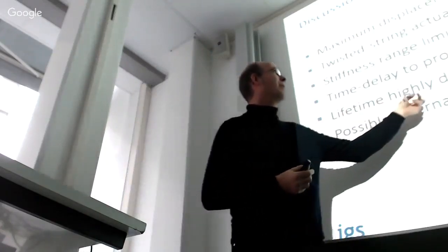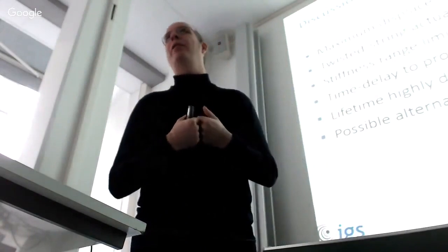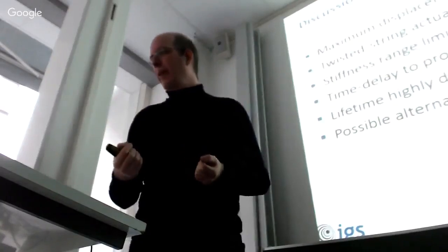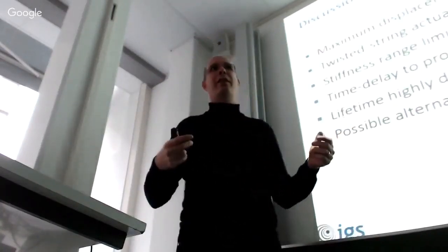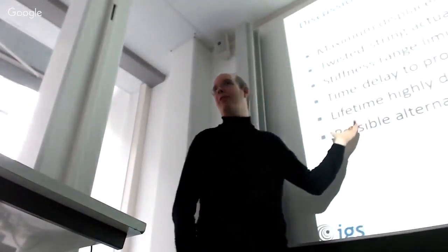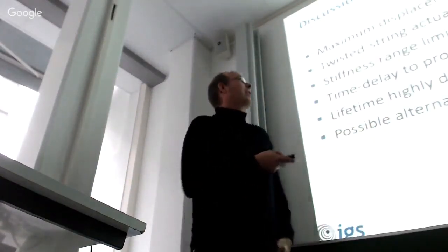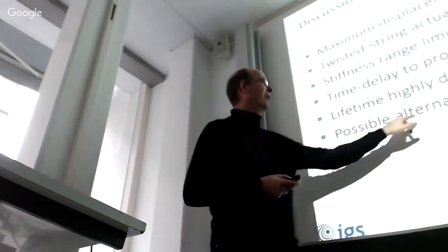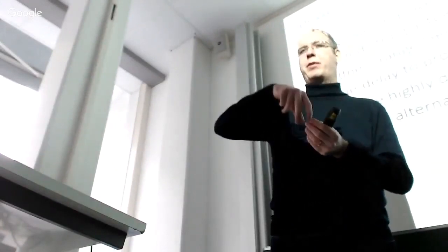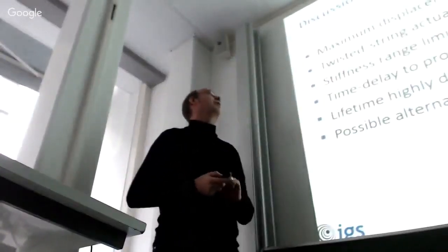And also, since we have the string materials, the examples we used cotton yarn fiber, we shifted to some stronger materials that are used in fishing lines, for instance. The problem is that we continuously twist this up and exert forces on it, so we have to start thinking about lifetimes, because this can become damaged and then actually fracture. So there are quite a lot of problems here. That's why we currently look into an alternative, just with a ball screw mechanism, maybe with a screw, and then something that's linear and moving on it, and we start rotating, which avoids several of these problems.